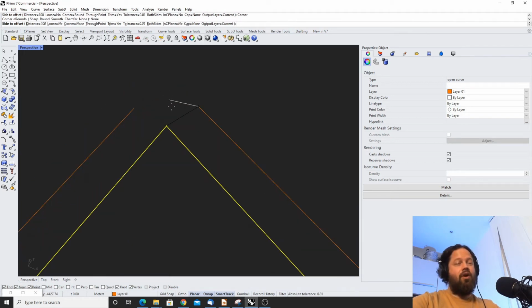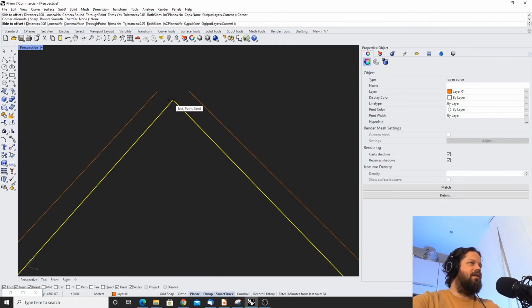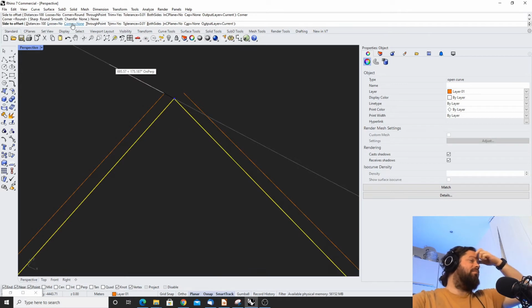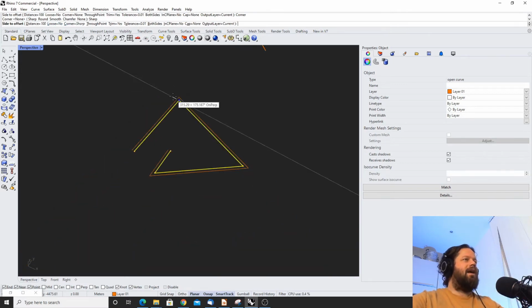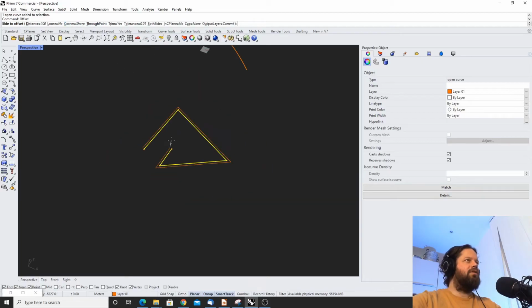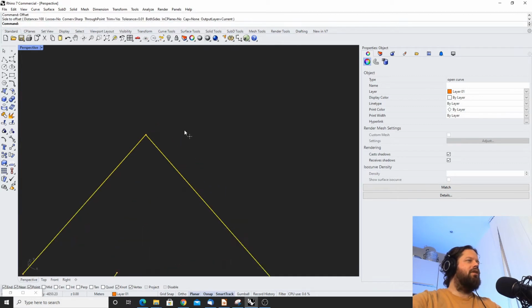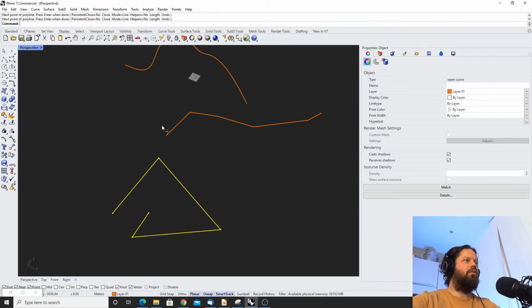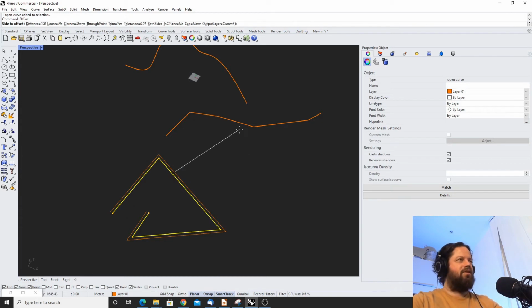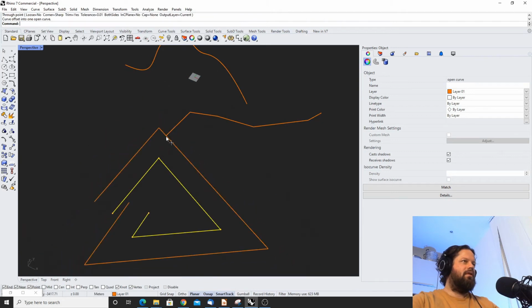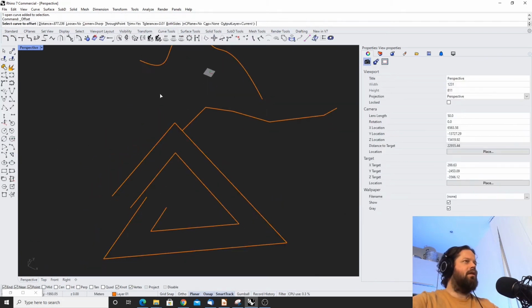And you have the option of none, which just basically offsets each segment without connecting it back together. I normally use this one, that's just a normal simple offset. Another option is here, through point. So if, for example, I have another thing here and I want to offset it through a certain point here, then I can offset it like this, offset, and then normally I just type T and then it offsets it to the position I want. I use that very often.